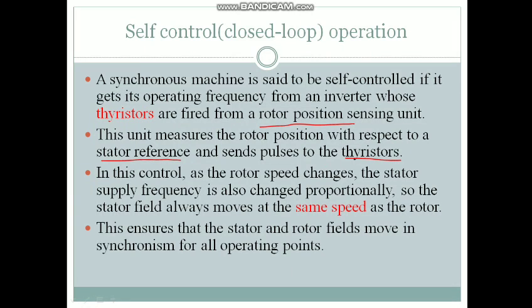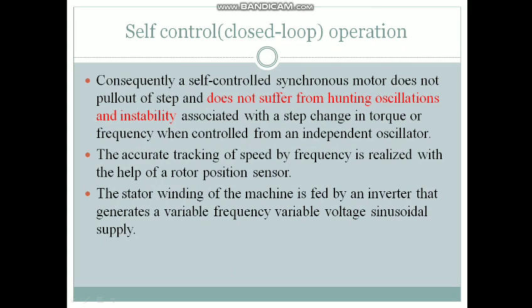In this control, as the rotor speed changes, the stator supply frequency also changes proportionally according to the rotor position, so that the stator field always moves at the same speed as the rotor, and we have our synchronous field. This ensures that the stator and rotor fields move in synchronism for all operating points.